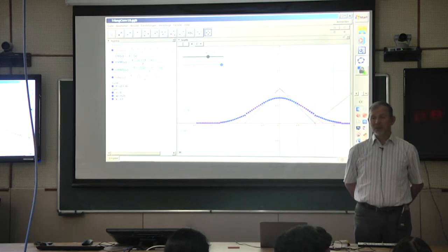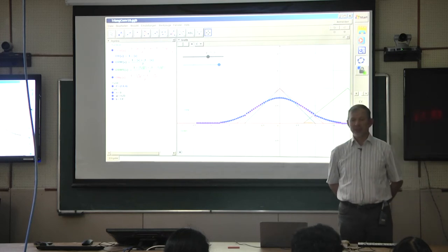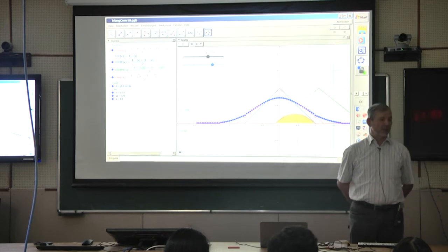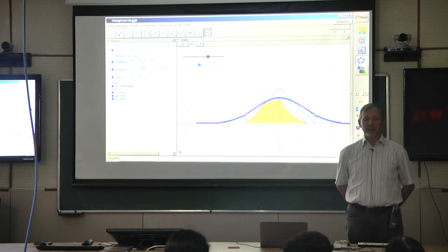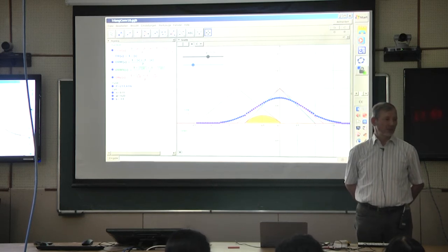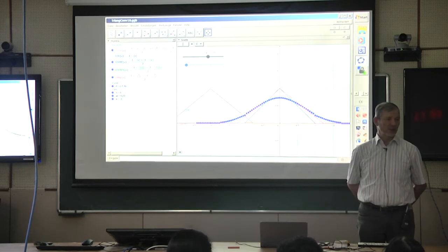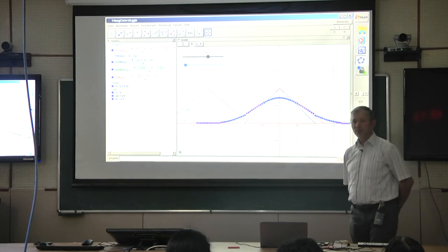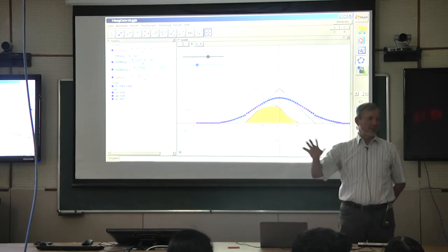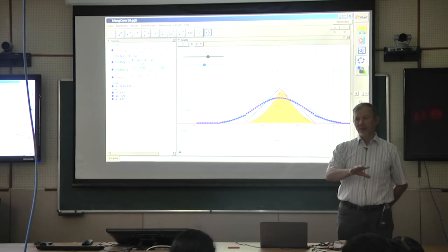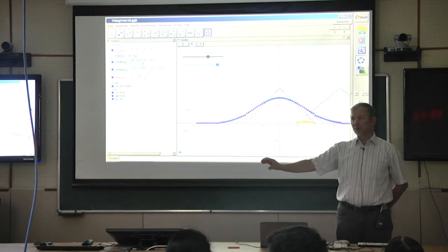And within that space, the closure of the test functions, which for now means compactly supported continuous functions, is maybe the easiest space. So this is what we call C0, the space of continuous functions vanishing at infinity. So we have BIBO systems which map bounded functions into bounded functions, decaying functions into decaying functions, and we can even control the maximum of the output by the maximum of the input.